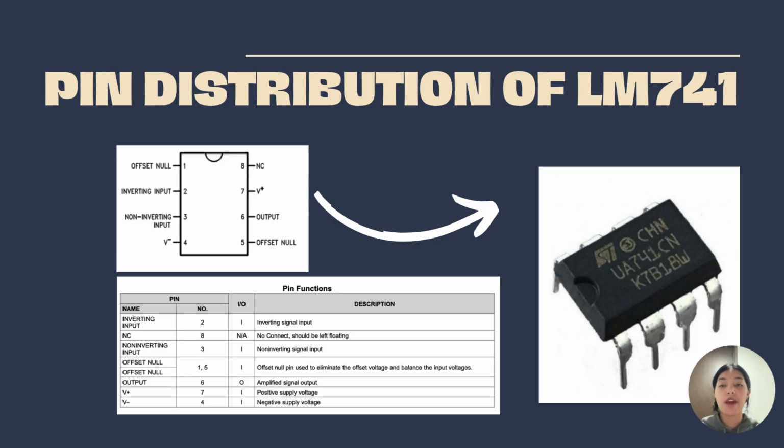And finally, we have the pin 8 that is not connected. This pin has no internal electrical connections within the LM741. It is present in the package but does not serve any functional purpose. So in many cases, it's unconnected because it doesn't have any impact on circuit performance.